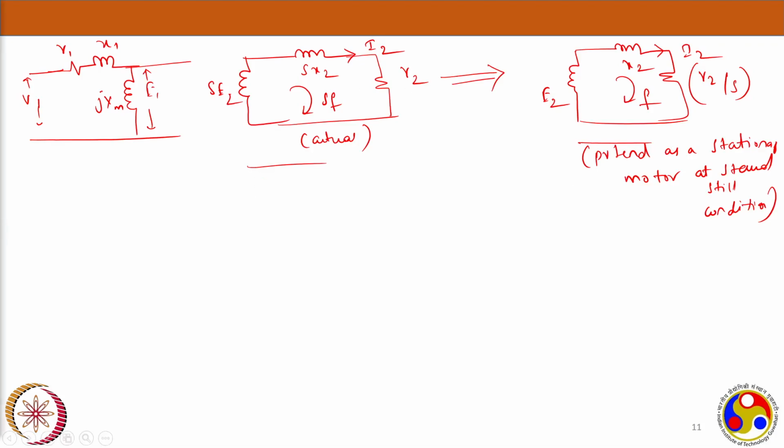Now see, in the secondary and the primary, you have the same equivalent circuit. So now E2 will be there, with the same frequency. You can just join these two by multiplying by the turns ratio. Because E1 and E2 are here, slip is not a problem anymore, and also the frequencies are the same. Now the equivalent circuits can be combined.